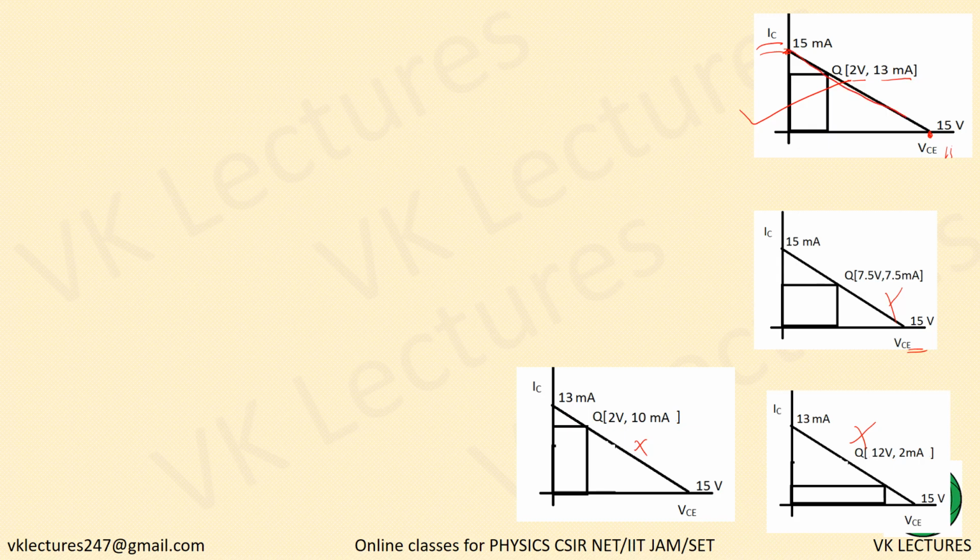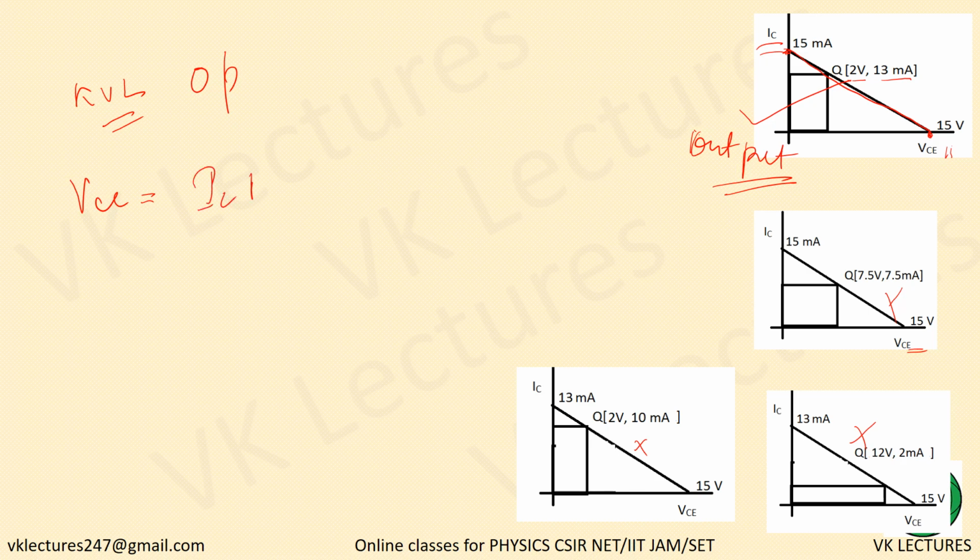You draw a line connecting those from the input output side. Why output side? You apply KVL to the output. What you get? VCC equal to ICRC plus VCE plus IE into RE. Now this I can write as IC into RE.